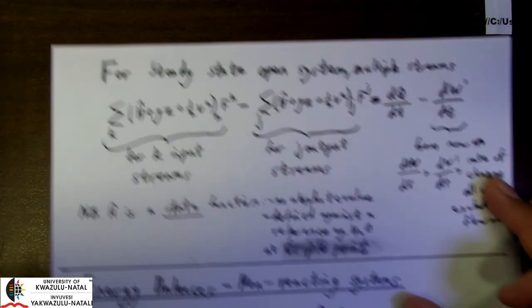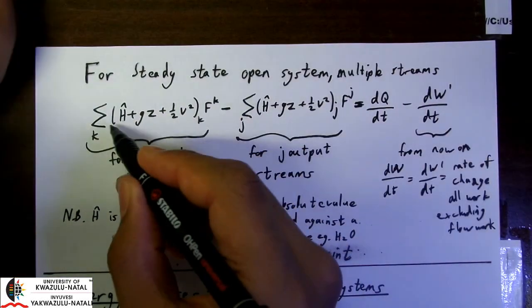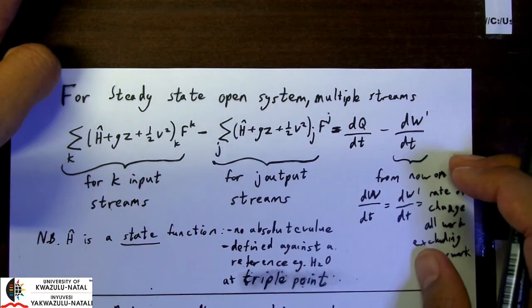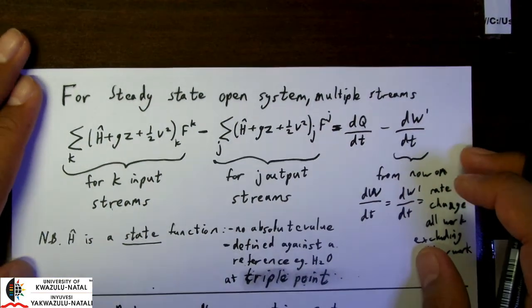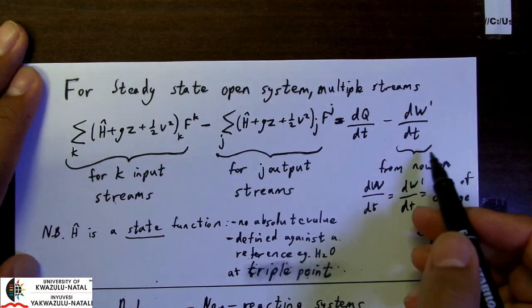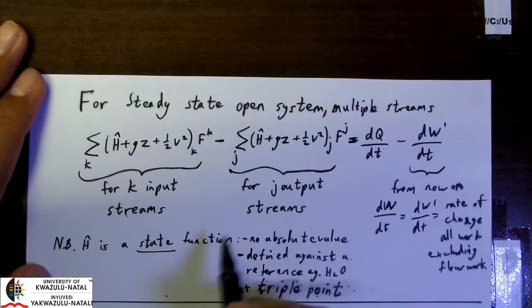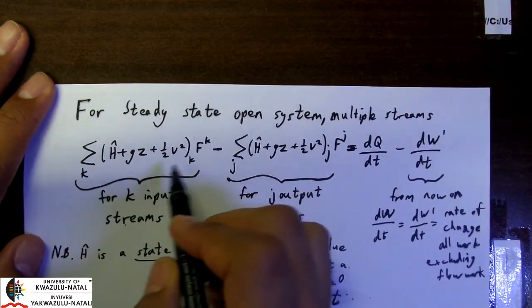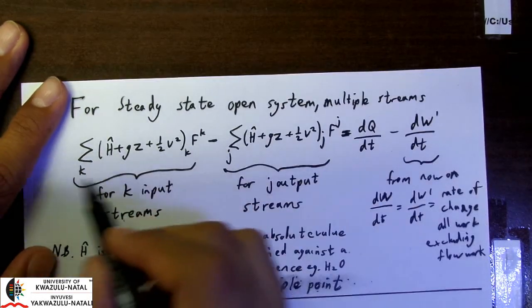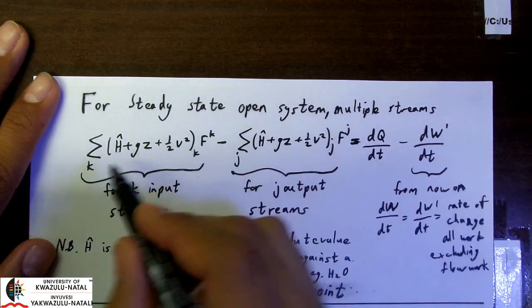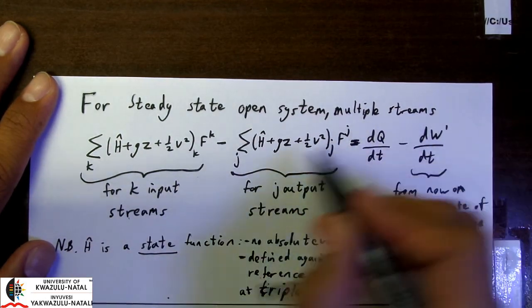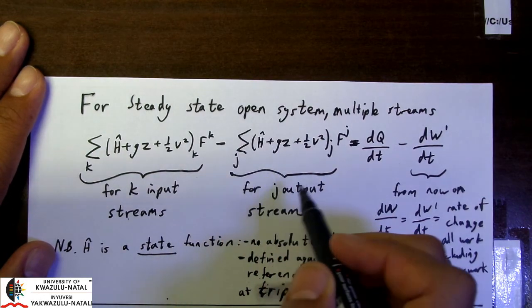So to write this out once again in enthalpy terms, we are grouping up our U plus PV, and we obtain the following general equation, which is perhaps the most important equation which you will be using for energy balancing. So we have our input of energy minus our output, rather our inputs of our input streams here and the dq dt, as well as our outputs.